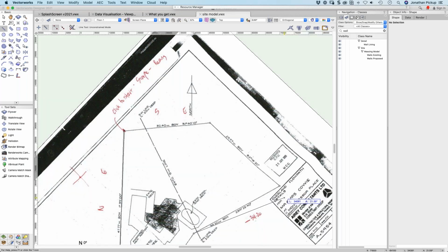Let's go to this one. Okay, so this one is the distance 34 m. 34.2 m tab. And this is northing and easting again. And we're going to go 239 degrees, 23 minutes, 40 seconds. Tab once. Now that's pretty close, Jane, isn't it? That one? Yeah.